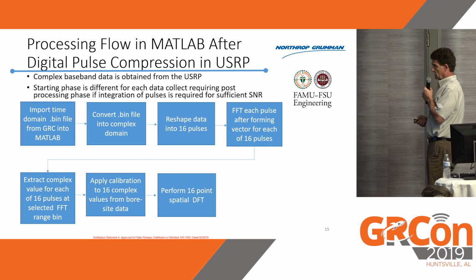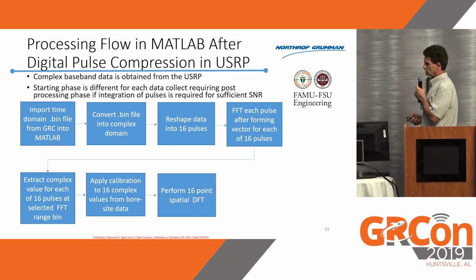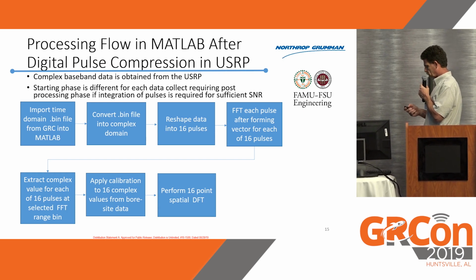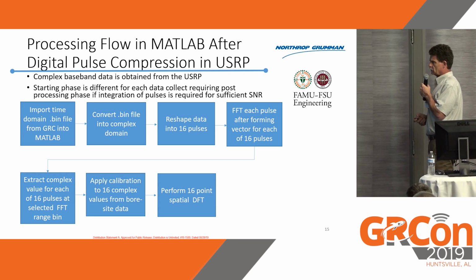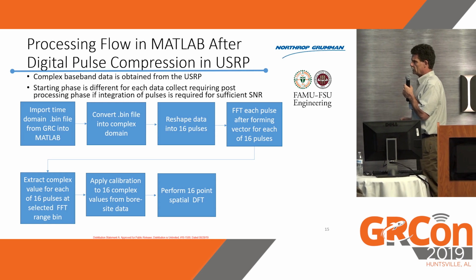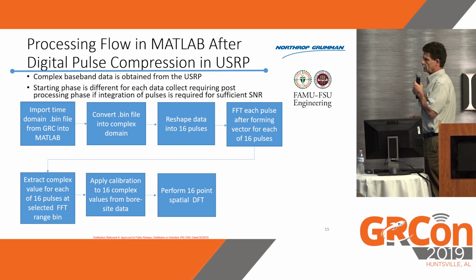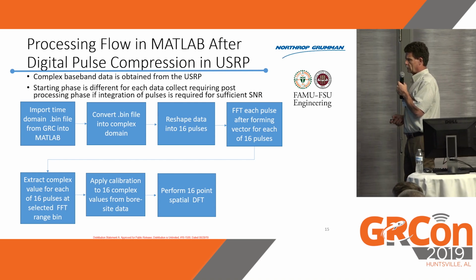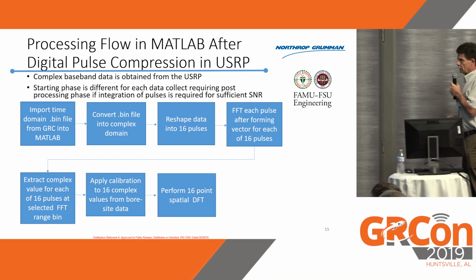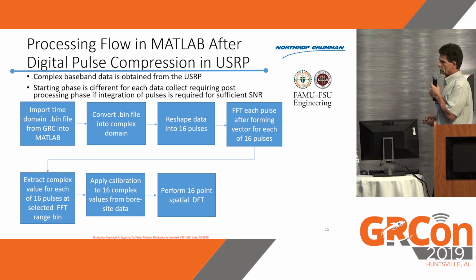So the next thing we did is, this is where we had to stop in terms of using the graphical companion. And we went into Matlab, but we could have easily gone into Octave. There was nothing too fancy here. So what the students then did is they took the 8,000 samples that the GRC produces as a binary file and put it into a complex domain into Matlab. The samples end up getting interleaved, so you have to move them around appropriately with a little bit of code.